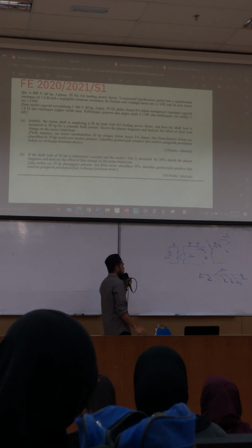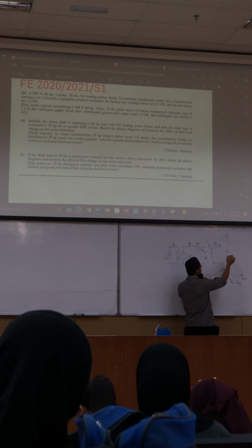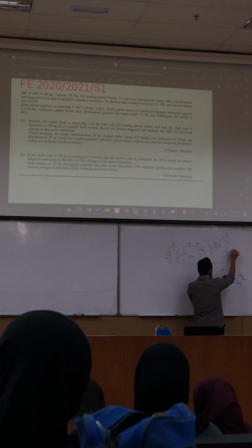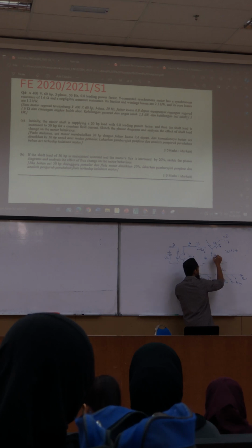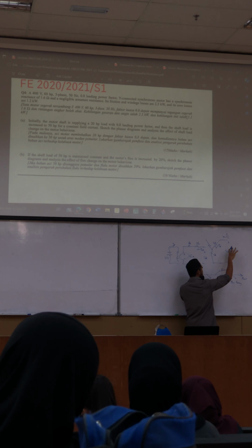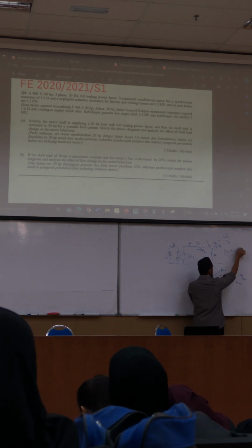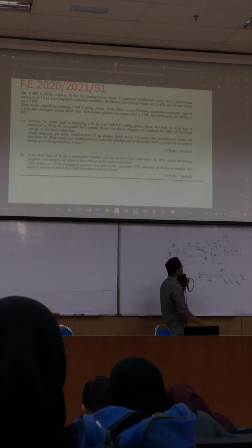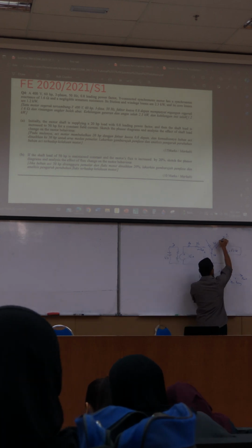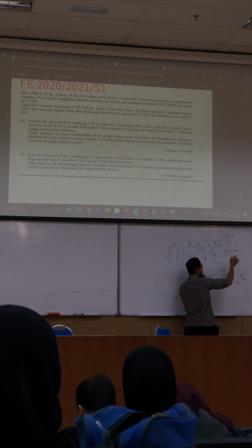So when you sketch, derive the formula. V_L is equal to root 3 times your V phase. This is your V phase, so V_L should be bigger, higher. So how much higher is it? Times root 3. This is your formula derived from this diagram. I load, because it just follows the same line, is equal to I phase.